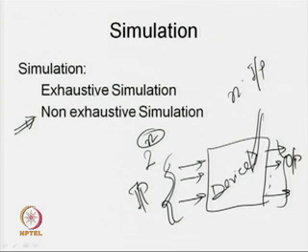In case of exhaustive simulation, we try to test it for all possible combinations, but due to the large number of input combinations, because the input pattern is exponential in the number of input signals, it is not possible to test the entire circuit for all the possible combinations. So, for that we go for selective simulation, and we say this is non-exhaustive simulation.